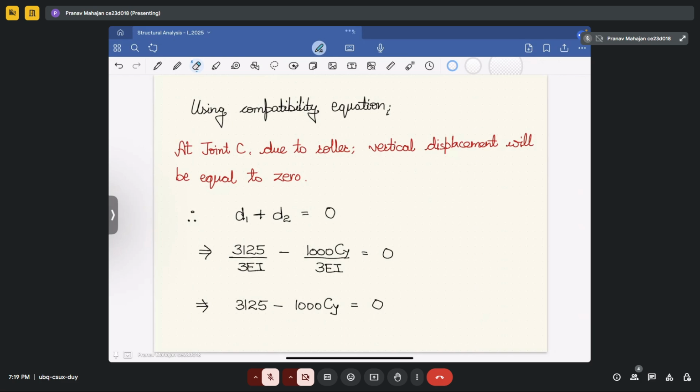So this is how you will solve all the problems related to force method, and with an increase in the complexity of the structure, all the calculation will become difficult to solve. I am not telling you about this coming week, I am talking about the 12th week. In the 12th week you will see that if there are a number of redundant forces in the structure, then you can't solve the problem directly by applying the force method. You have to use the flexibility matrix method.